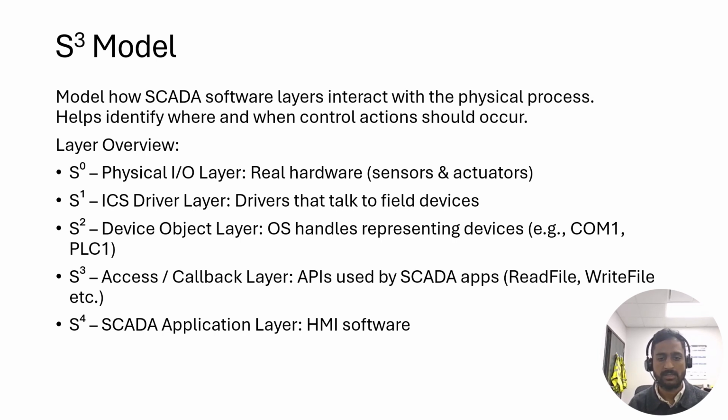Then the access or callback layer. These would be the APIs or protocols that SCADA uses, let's say Modbus read register command or write register command. And then the SCADA application layer, which is the HMI graphics and such.